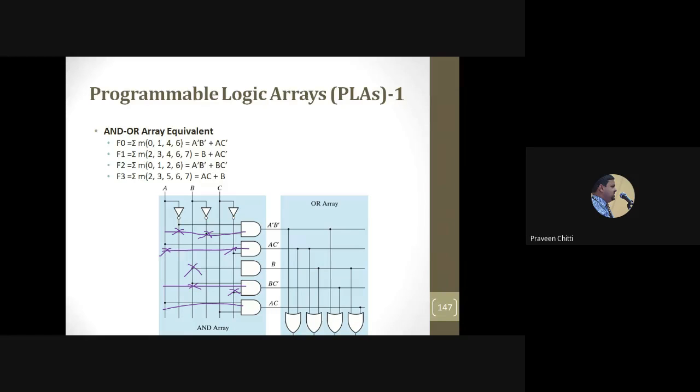And for here also, you can show it as A. Here one you should show, and sorry, for this line, and then you should show it as C. Similarly, here two are required. You can show like this. One line itself, this and this. Only one line you can show for this OR gate instead of showing two. Then similarly, you can show only one line here. Take this and this. Similarly, for this also, you can show only one line and you should mark these two. And here you can show one line and you can mark these two for that. And that is the construction of the programmable logic array, right?